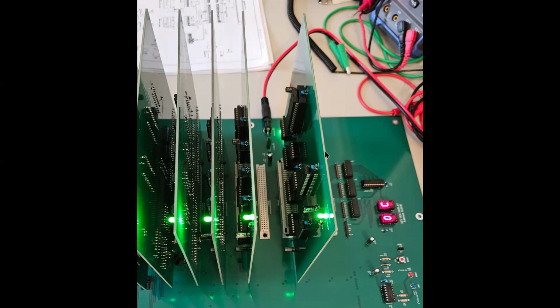the memory card can run in any of the expansion slots. So that's what I did. I popped the memory card into our first expansion slot as a test to verify again that the memory card passed regression tests in the expansion slot, and that also verified that the expansion slot was wired correctly. So, okay, that's it. That's our issue, and that's the fix.